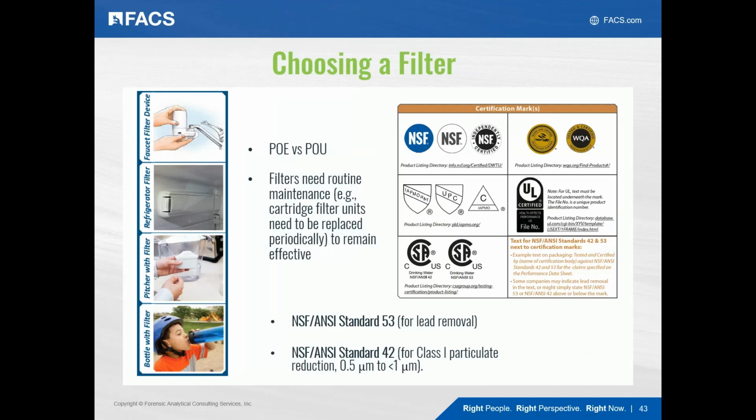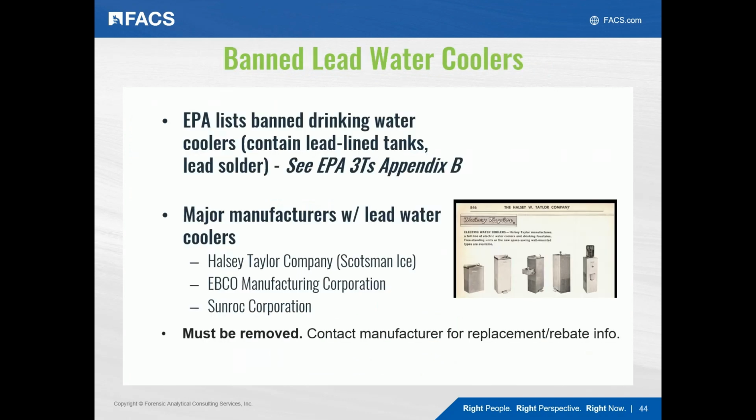So some schools are choosing to go ahead and install point-of-use filters at their drinking water outlets, particularly at the bottle filler stations. So this is one option. Just make sure to select filters that are certified to reduce lead. Check with the manufacturer or a third-party website, such as nsf.org, to verify that the product is certified to remove lead and to remove particulates. And of course, stay on top of filter replacement.